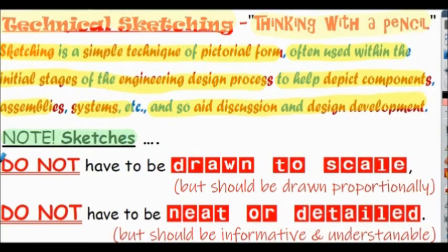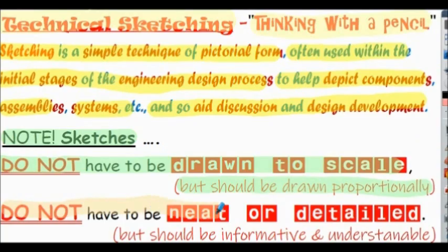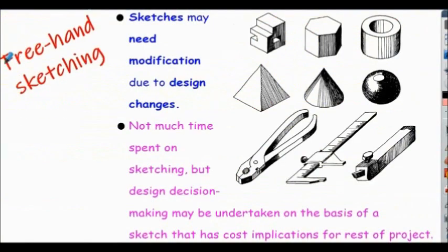Note that sketches do not need to be drawn to scale, although it's strongly suggested they should be drawn proportionally to provide realistic representation, and sketches do not have to be neat or detailed, but they should provide enough information to be informative and understandable. Here's a few illustrations of what's termed freehand sketching.